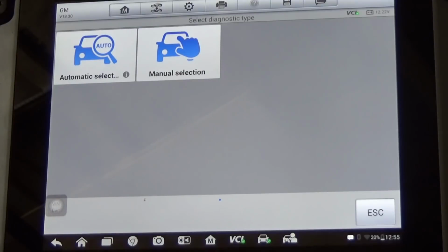On this particular vehicle, we have an evaporative emissions code that is being set. Now this is setting at P0446 for canister vent valve performance. And as you're going to see as I show you some of the data, there's more than one thing going on with this car with the evaporative emissions. Let's go see what codes are setting in this car.